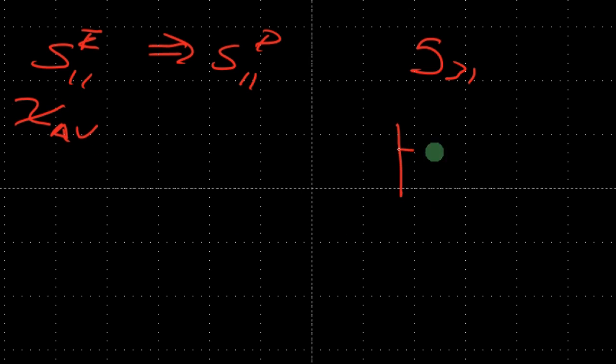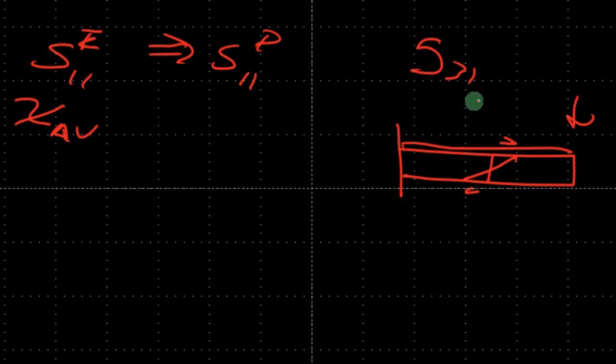So if we had our cantilever, and at any point we have some type of stress distribution, maybe this is tension, this is compression here. We calculated now the average of this, and if you're drawing the tension on the top, you put a force here, the tension on the top is going to look like this. We'll call this level of stress, it's going to decrease linearly. It's going to be the highest here, and it's going to be actually 0 at the tip. So the tension force is going to be linearly decreasing. It's going to be maximum here.